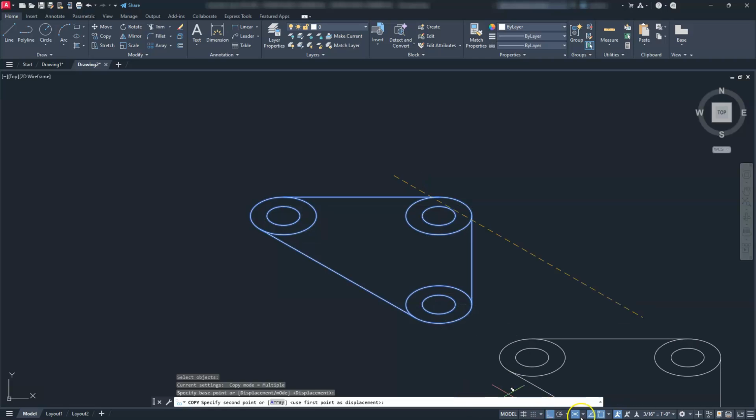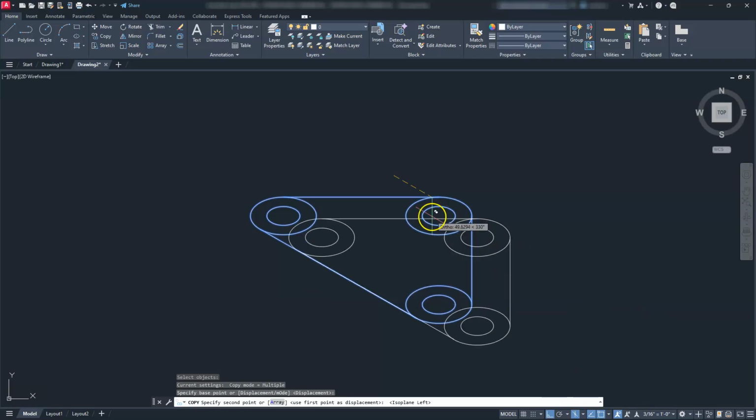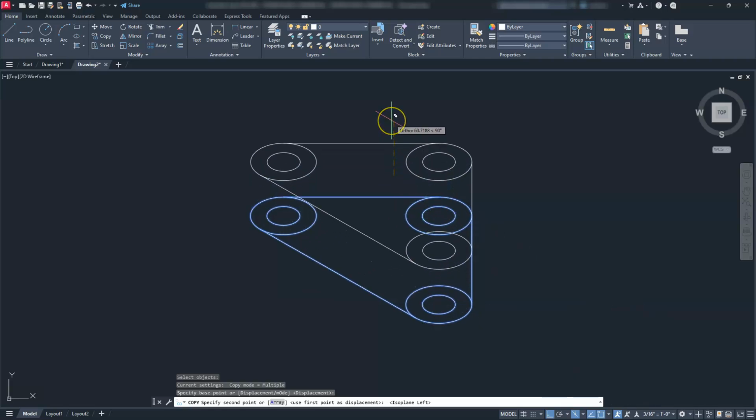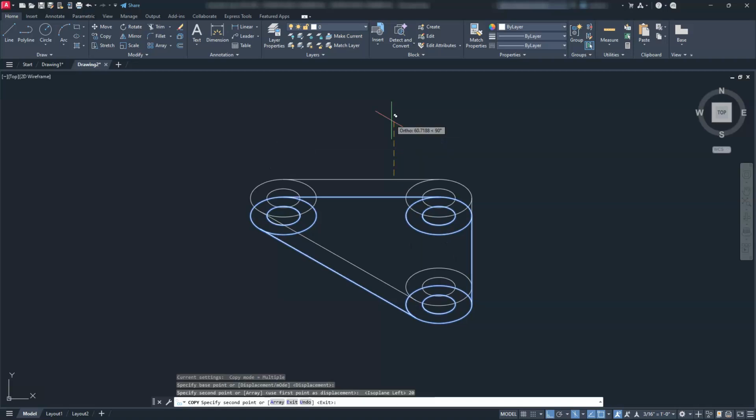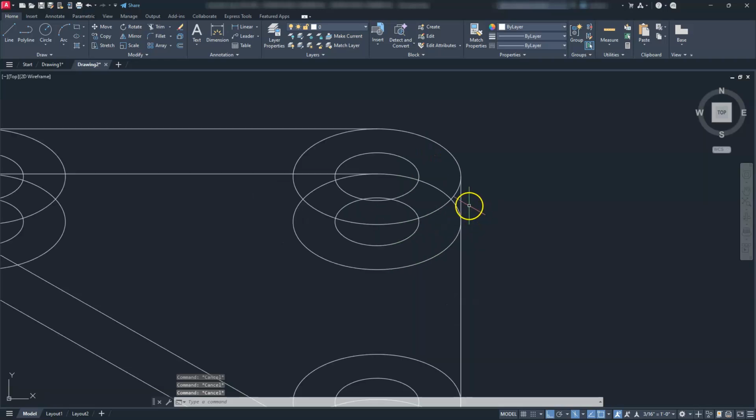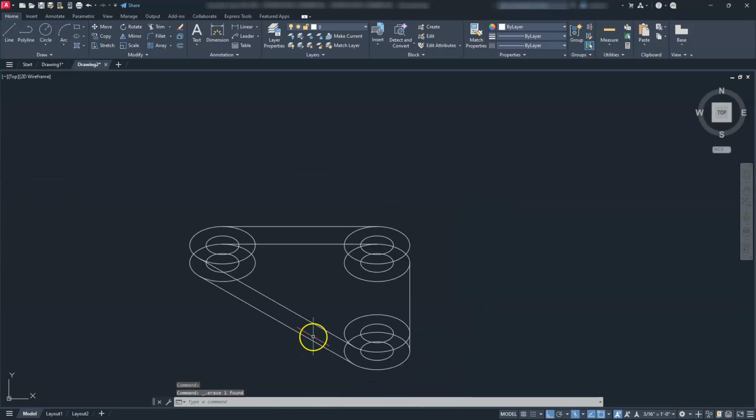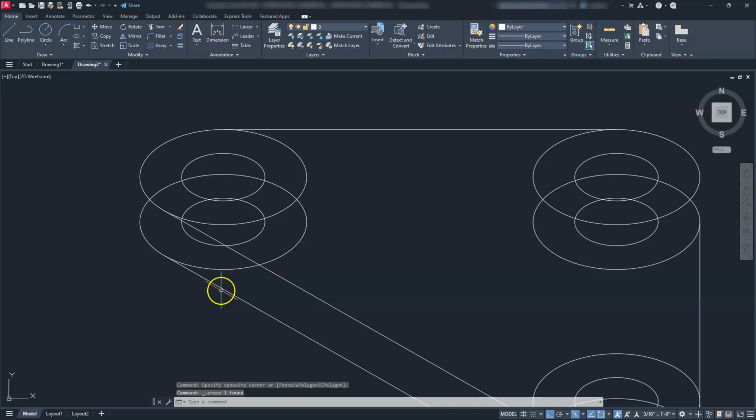Now I will have to switch to an isometric left or an isometric right. So let's just go ahead and go to isometric left. I'm going to go up a distance of 20. Right? And now I will stay here for a second. All right, this is going to be a double line. So I'm just going to automatically delete that line because I know they're going to overlap. These two lines we will see, but this line here underneath will not be seen. Okay? So hopefully everything so far, you're following with me.